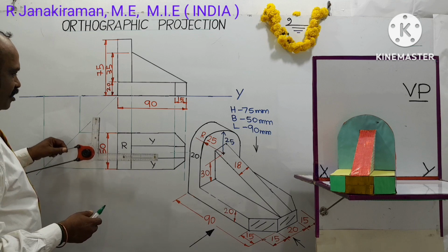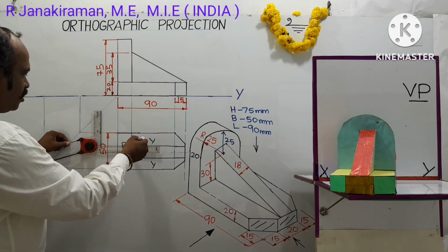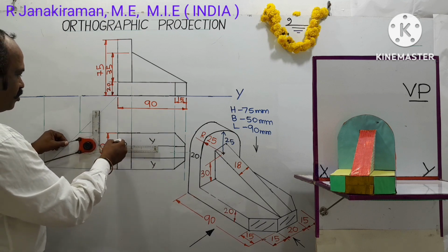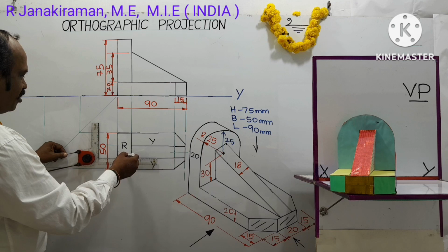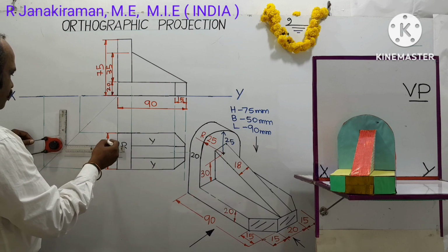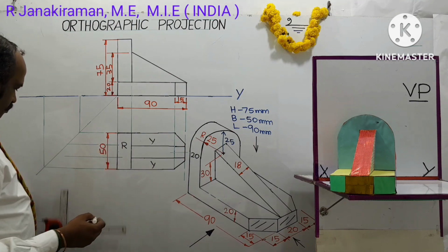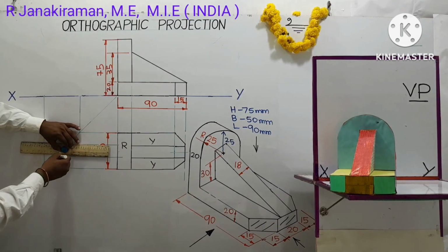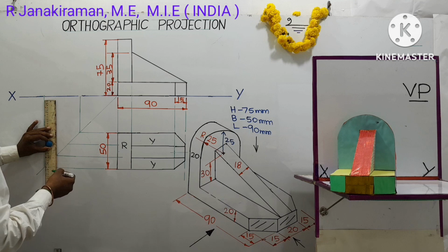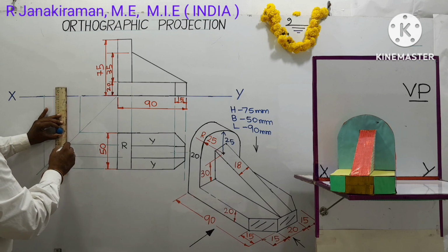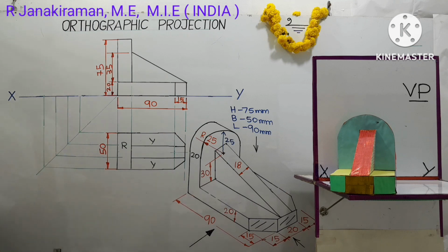Okay, then you trace out this previous triangular part thickness 18 mm, which shall be drawn using 2H pencil line or projection line, where it intersects with the miter line. There you draw vertical projector up to this XY line. Understand? So these projection lines are used to trace the breadth of the object.